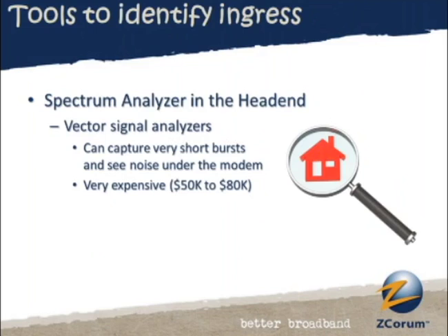A VSA is something that has the brains to actually decode the DOCSIS signaling, and this is important compared to just a regular spectrum analyzer, because if I'm looking at my cable signaling with a regular spectrum analyzer, I can't really tell the difference between what is the cable modem talking to me in the head end versus what is a source of noise that's in that exact same part of the frequency. A VSA can see those two things.